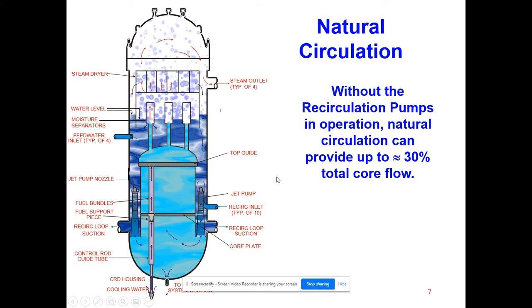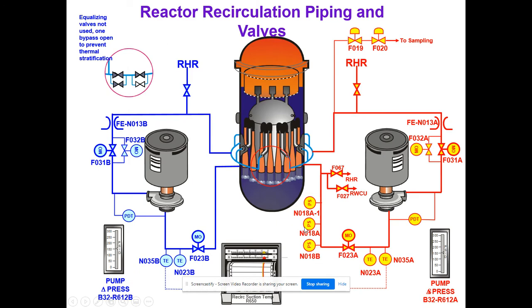That's not something you're going to do in a normal situation, but that's a huge amount of water to be moving around just from natural circ. But that's how much heat is actually being produced in here. And anything hot, water, hot air, both going to rise, and they'll displace whatever's up here and make a nice little natural circulation loop there.